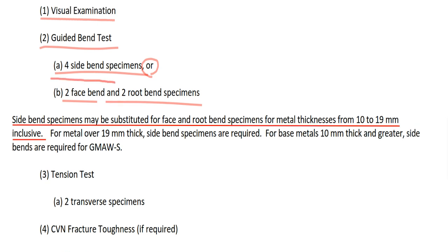So no 2 face and 2 root bend specimens for 10 to 19 millimeter, but just 4 side bend specimens can be taken.